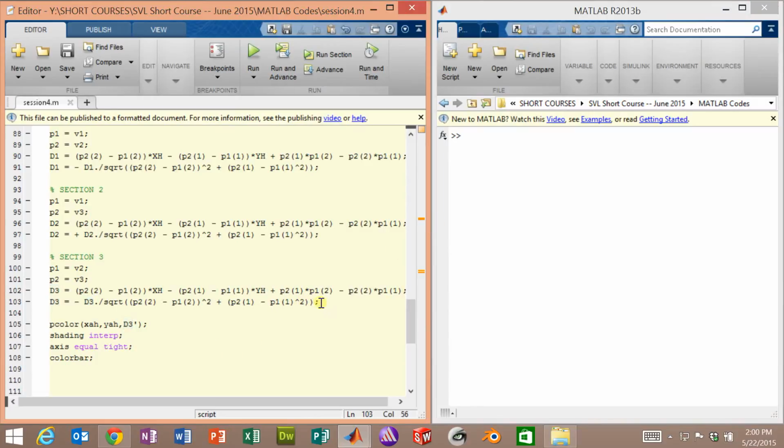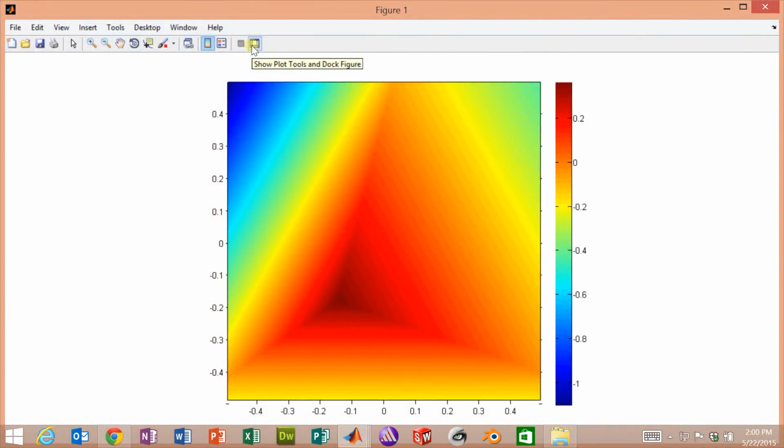Now from here, we want to combine all three of these. So here's where we actually build the unit cell, a grayscale unit cell. So UC for unit cell, we'll take the minimum value of D1, D2, and D3. Now min doesn't like us to have 3 input arguments, so we'll just say UC, comma D3. That'll take the minimum value from all 3 of those. Let's go ahead and look at what that would look like. A little bit lopsided, isn't it?